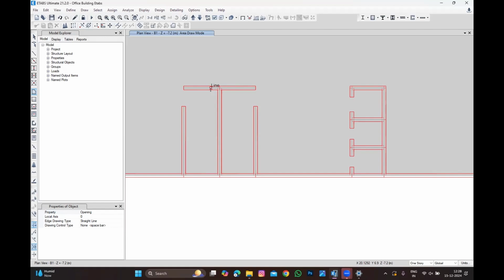In a high-rise building, which load is going to govern the structure, if you ask me? The straightforward answer: it is not gravity load. The lateral load is going to govern the high-rise building. So the most important thing is the lateral force. From the beginning I need to take care of the lateral force to reduce the reinforcement. Gravity doesn't matter.